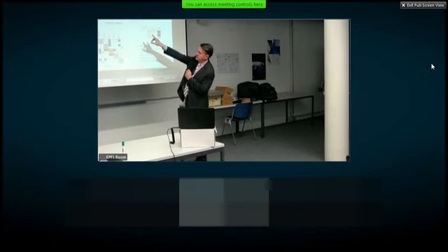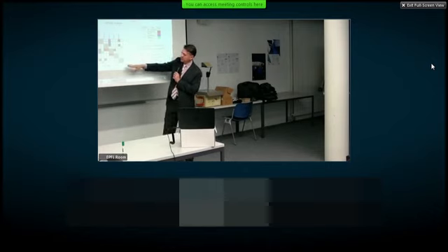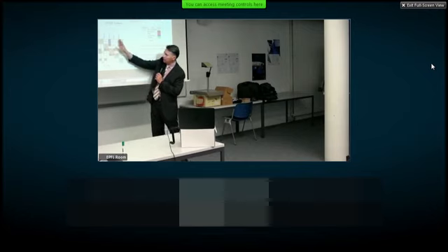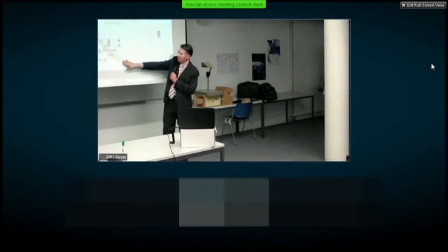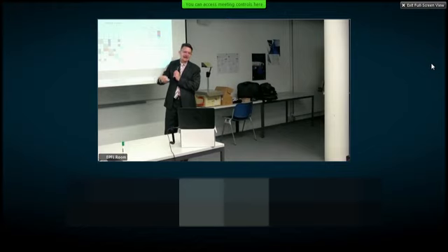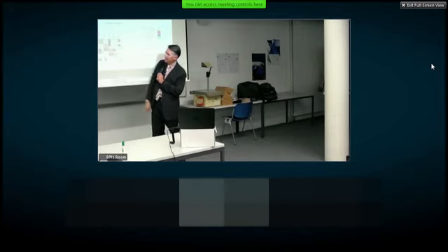The block diagram on the upper left contains the exact same information as this matrix. A DSM is always a square matrix where your components are the rows and columns, equally labeled. There's no information on the diagonal, since a component connects with itself, so you keep the diagonal blank. All of those interfaces and flows we mentioned are shown as off-diagonals.